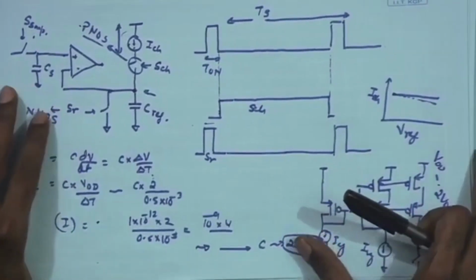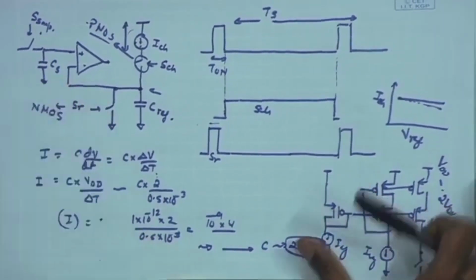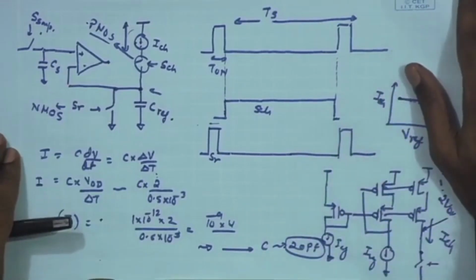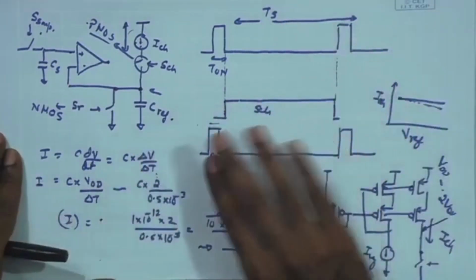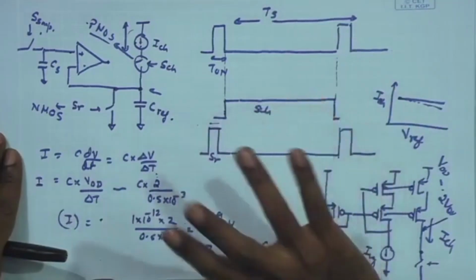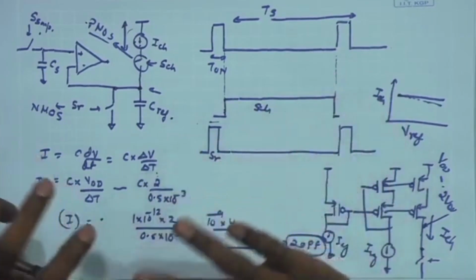So let us look into the comparator design and the transistor-level implementation, the issues associated with the choice of topology, the number of stages, the sizing, and along with that the non-idealities like offset. Before we look into the comparator design, it will also be useful to check out the specification of the comparator that we would like to use, so that we can have some idea about the design parameters and look at the practical numbers that we can have for the target comparator.